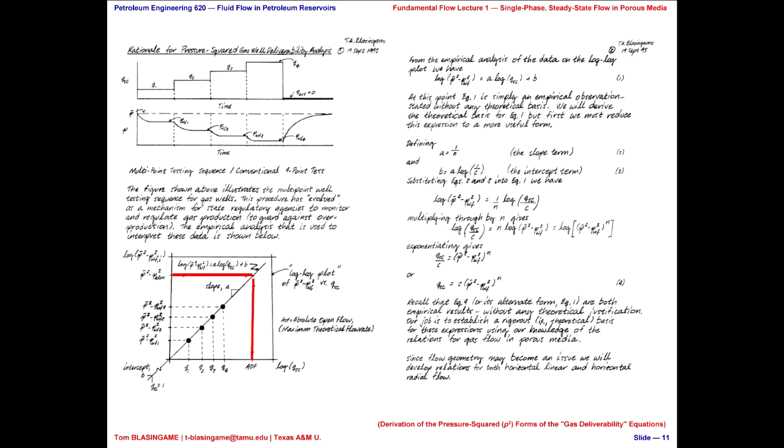So when you read the newspaper and it says that so-and-so has a new gas well and its AOF, its absolute open flow, is X, is that a real flow rate? No, it's calculated. So you have to be very careful when you're looking at other people's data whenever they report absolute open flow. Why does the government care about absolute open flow? I know we talked about this. No? Louder? Okay, that's good. It can define a variable or some sort of measure of productivity.